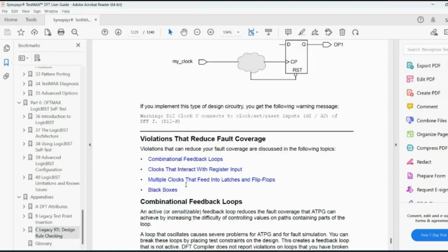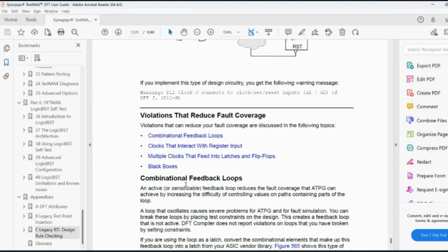In Intel Bangalore, I think it's pretty much a Spyglass flow. People use Spyglass at the RTL stage, identify any kind of design bugs, and give it to the DFT team for further DRC debug and synthesis.